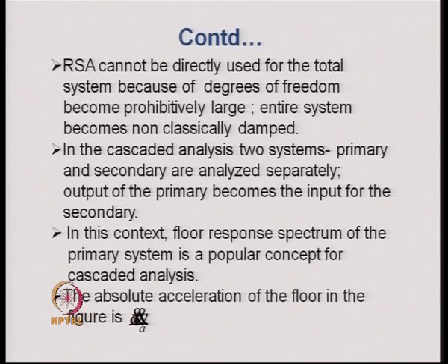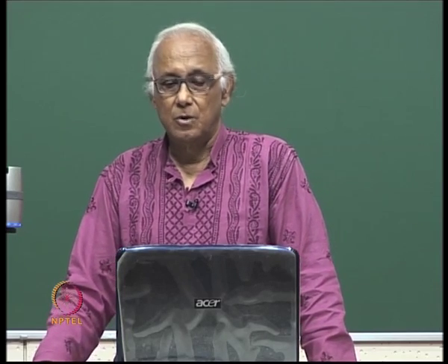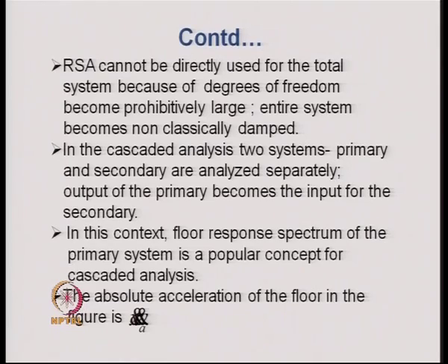Therefore, in the cascaded analysis, one can carry out a response spectrum method of analysis by decoupling the secondary system from the primary system, finding out the floor response spectra in case more than one floor is utilized for supporting the secondary system. At each support of the secondary system, if the excitations are different, then also one can perform the response spectrum method of analysis.